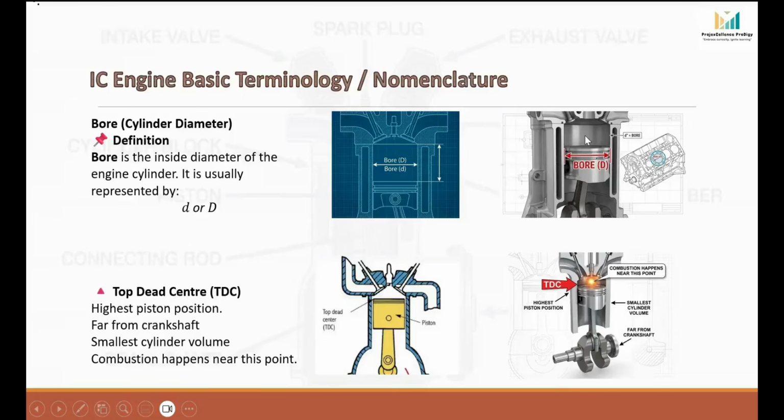During actual engine operation, over the time, the inner surface of the cylinder does not remain perfect. It starts wearing out. And this wear normally happens due to continuous rubbing of piston rings, high temperature and pressure, lubrication issues between piston and liner, dust or contaminants, and side thrust of the piston.